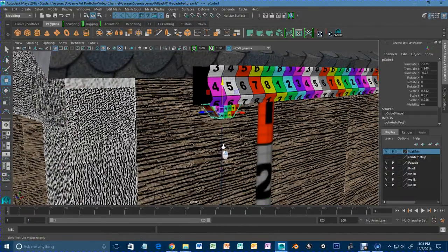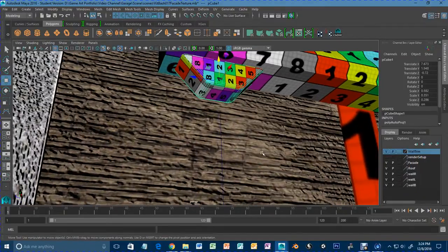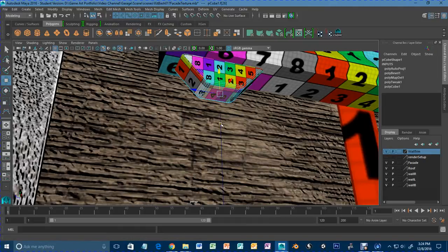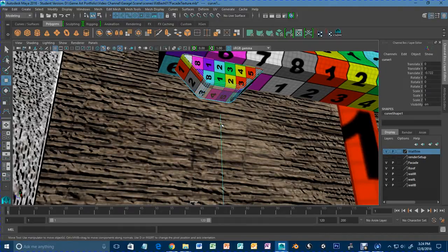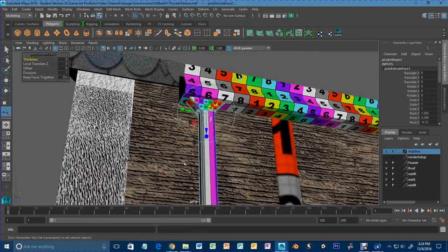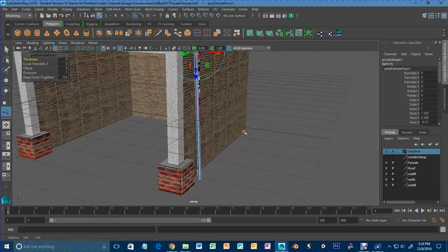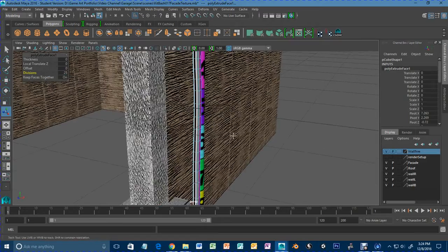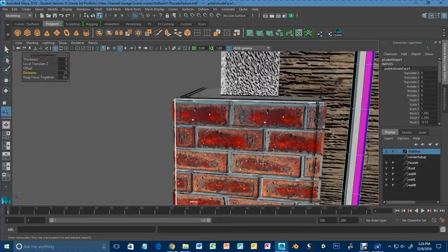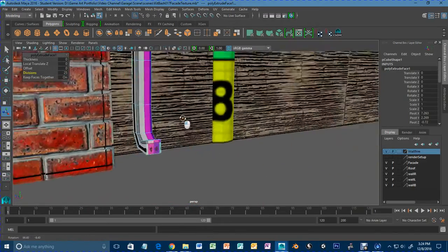Go to my object. I'm going to select this face on here. Then holding shift, I'm going to select the line. Now if I hit extrude, it's going to extrude that face out along that line. You see it goes straight from the start to the end because it only has one subdivision. We just crank up the subdivisions, boom. We get the pipe that we were going for.